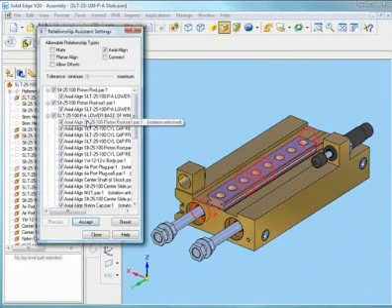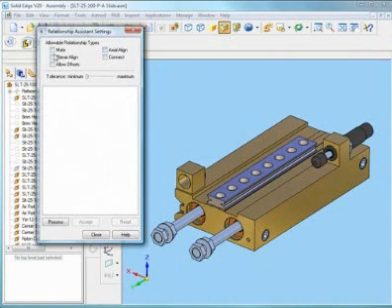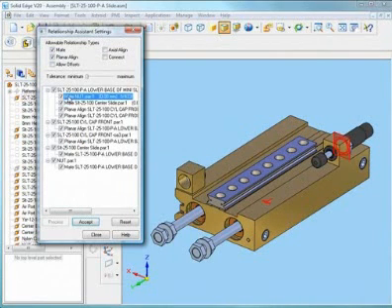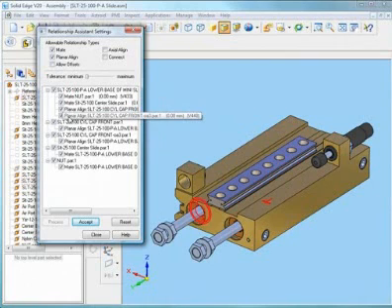After you define the select sets, choose the types of relationships to detect. First, we tell the system to find all the axial alignment relationships. You can deselect any relationships that are not required. For example, you want parts to be under-constrained if you want them free to move within the assembly.